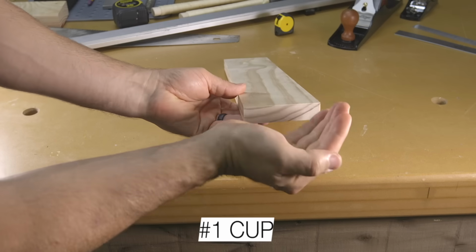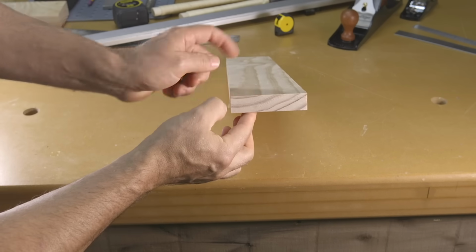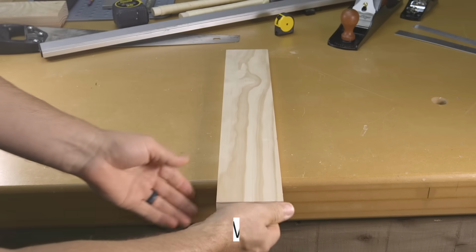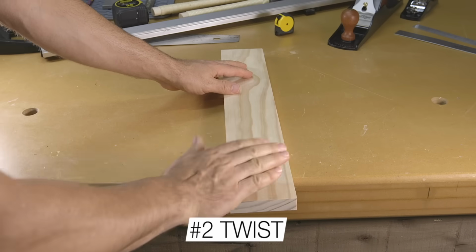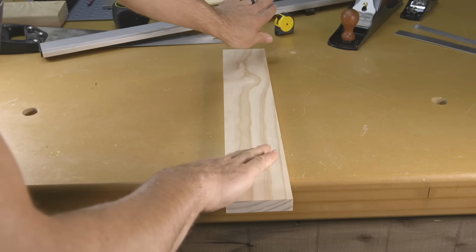Number 1 is a cup. A cup is when the board or the lumber is curved up in this direction on the face of the wood. Number 2 is a twist. A twist is when the board twists this way at one end and the opposite direction in the other.